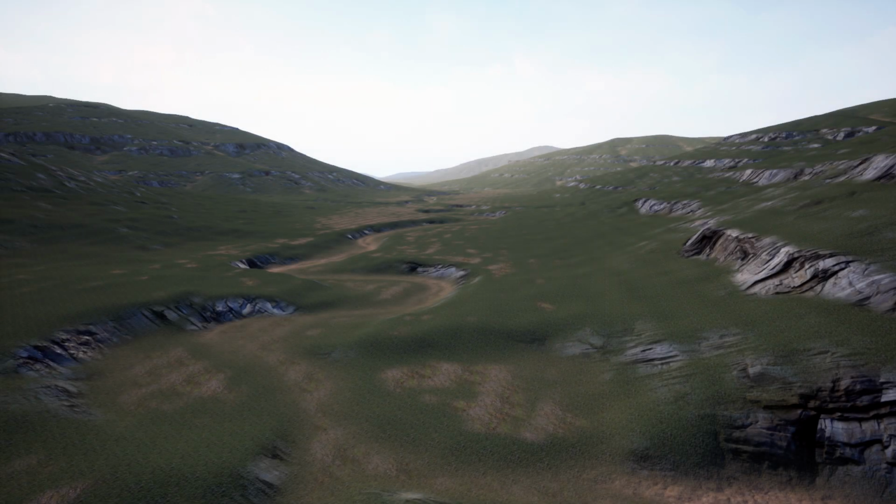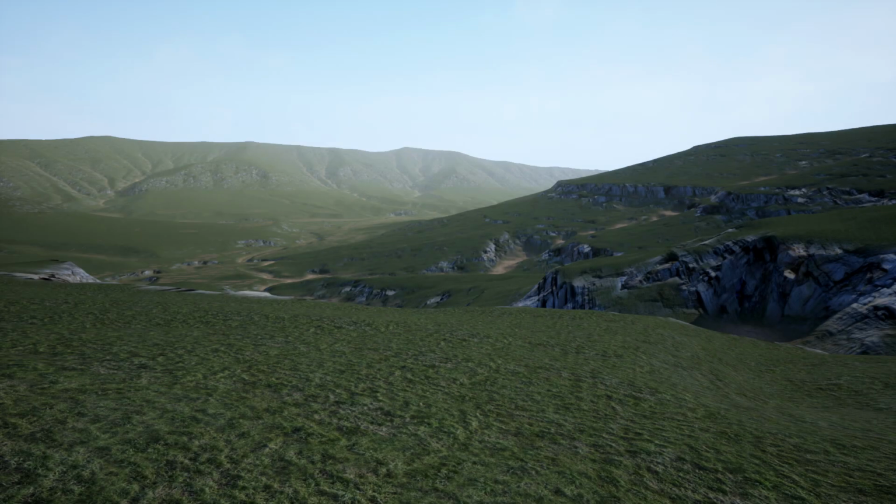For this tutorial, I have located a random USA coordinate 1 meter digital elevation model from the USGS NED online repository. I chose 1 meter resolution since that matches perfectly with the default 1 meter landscape vertex resolution. This gives us a landscape in Unreal Engine that is of the same resolution as the real-world location. The source digital elevation model was in GeoTIFF format, which can be imported directly into TerreSculptor Professional.